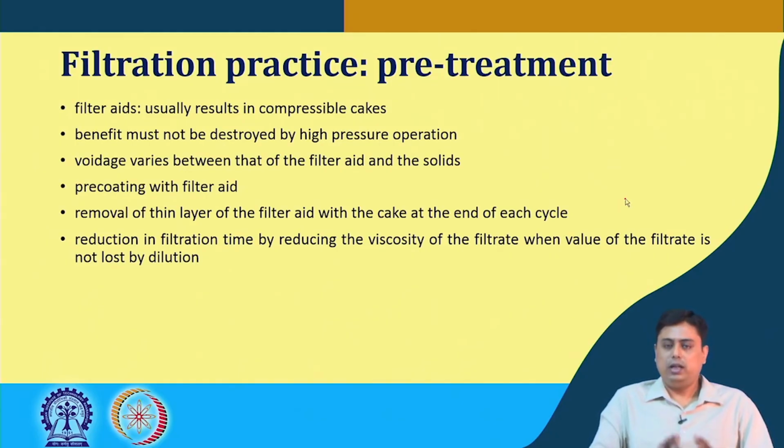So, these are typically the filtration process, and of course, after filtration there is the washing process that we have already discussed. In the washing process, particularly in case of compressible cake, the channeling phenomenon can occur, because the compressible cake has a nature that changes with pressure. So, during this operation, the flow will try to go through a less resistance zone, and once it finds that, that zone increases with time and with flow, and this is called channeling, the preferential path for the flow.